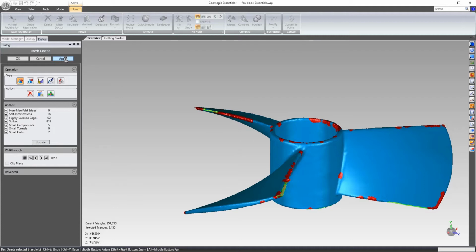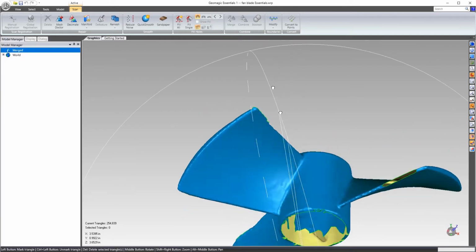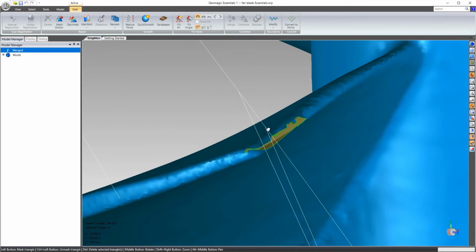Those green boundaries are showing that there are some hole areas that we can repair. So the next step after this mesh doctor finishes is taking the data there and filling the holes for those green boundaries. So if I just give it a second longer here, it will finish repairing those areas, and you'll see it'll have all zeros there. So now if I just look around, you can see that there's a couple of holes.